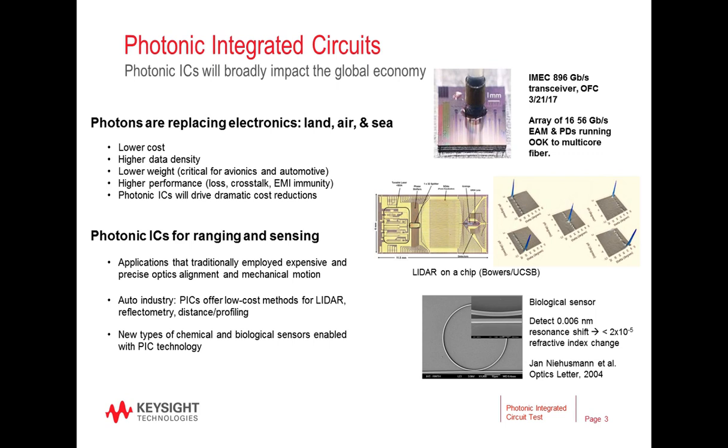Other applications include compact laser sensors for automobiles. An example is the UCSB LiDAR PIC on the middle right that is able to rapidly scan an optical beam emitted by the chip in 2 dimensions as shown. This was accomplished by integrating on-chip tunable lasers, gratings, and phase shifters.